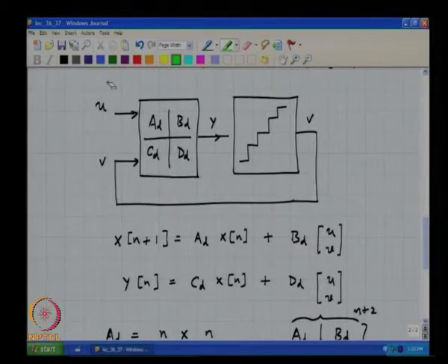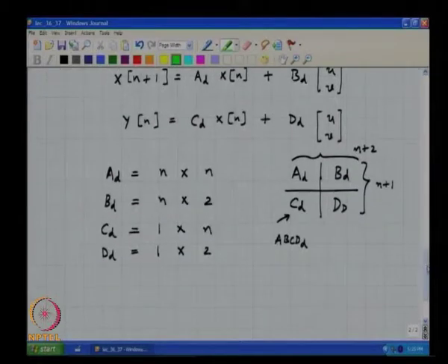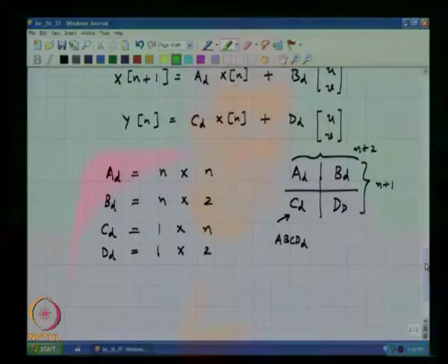So, what the toolbox does is implements this loop in C, so that the computation is very fast and interfaces with MATLAB, and therefore, the simulate DSM routine is actually very fast and very functional, right, where you specify the loop filter in state space form, for instance, give a set of random initial conditions for the loop state variables to begin with, and it does the rest.